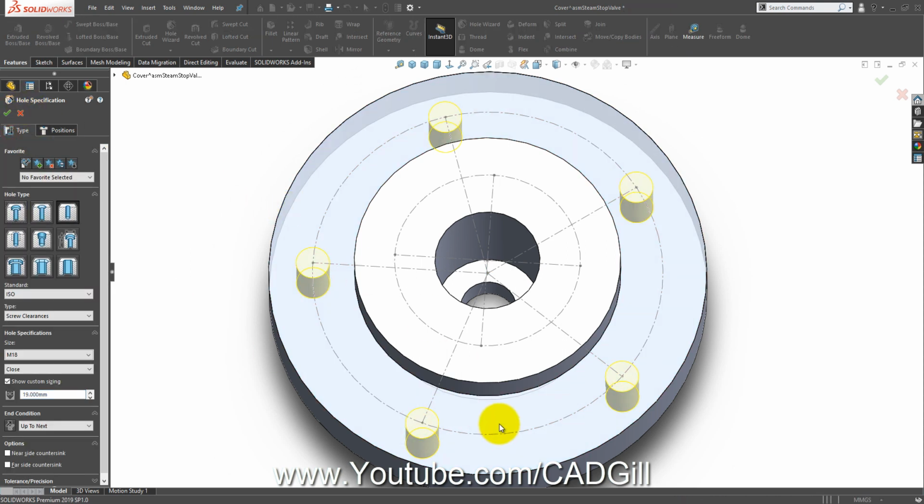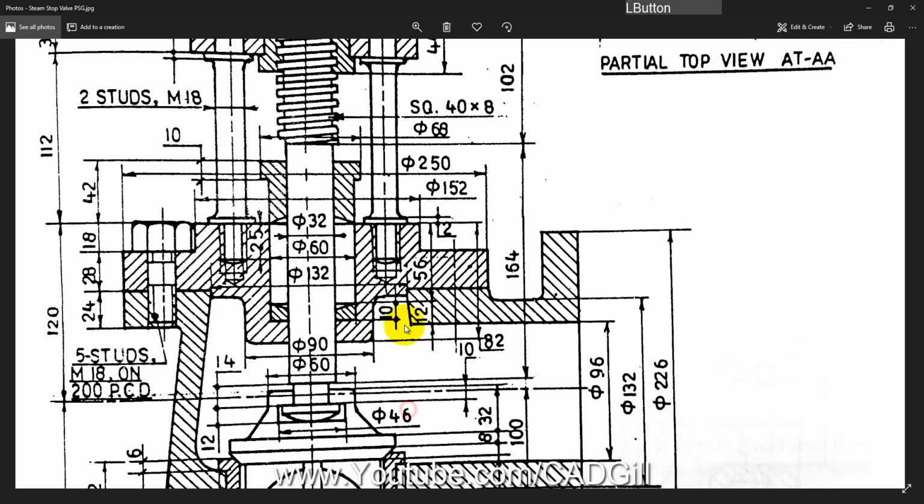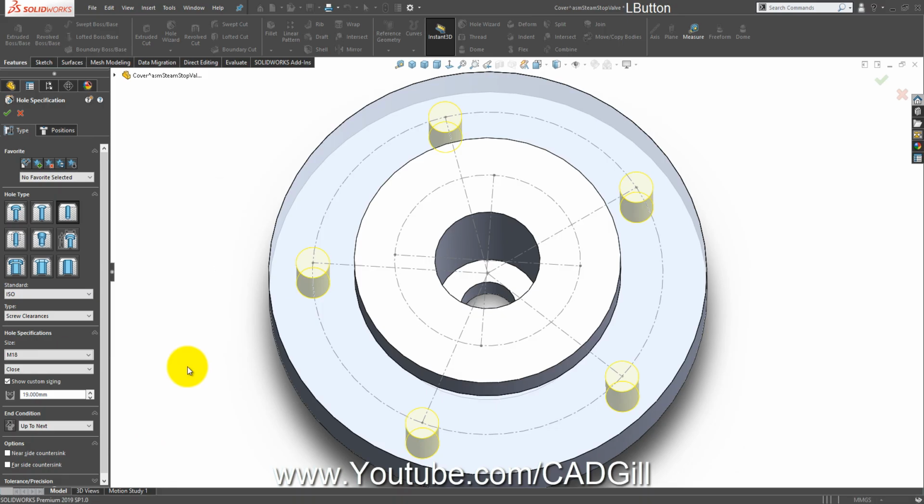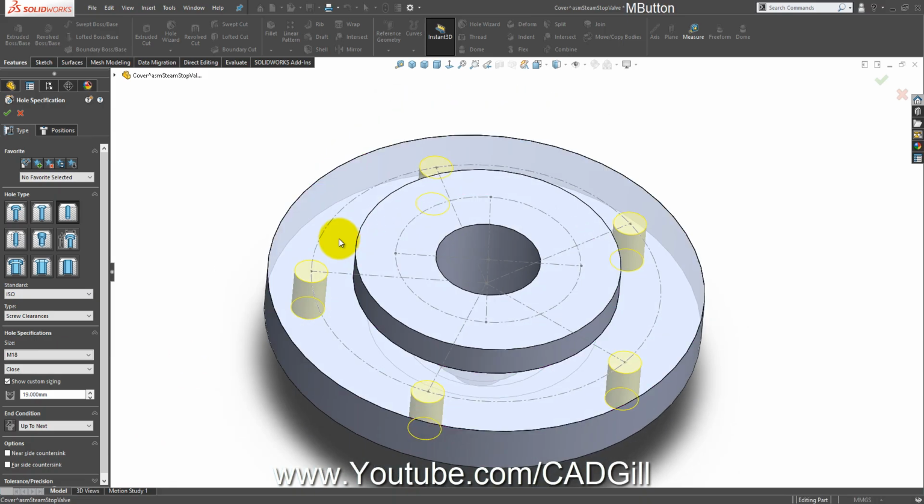But wait a second, let me see this again. Okay, this will align perfectly because there is a flange here. This tab here will automatically align with this, so 19 here is okay. If you made it 18 and there is some machining accuracy, it will have some problem with the alignment due to GD&T, wrong tolerancing.